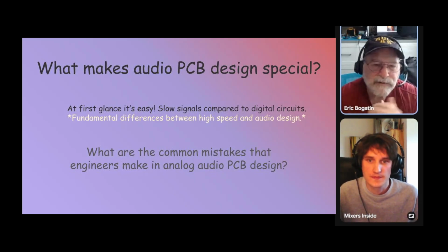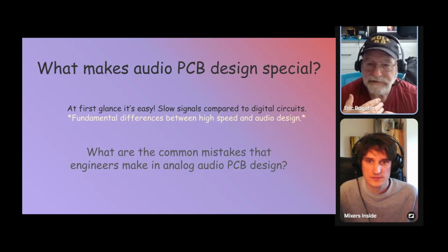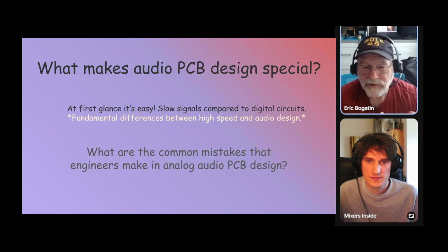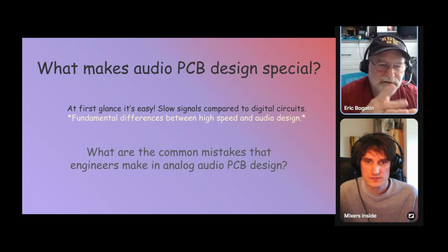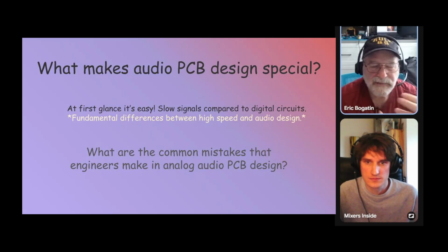But in low-frequency, low-noise design, if you have mixed signal, and a lot of audio systems now have a large amount of digital components, you have to keep in mind that the digital signals on the same board in the vicinity could have 1 to 5 volts of signal swing, and the audio signals may be in the millivolt range.